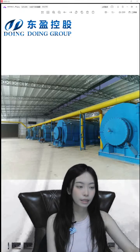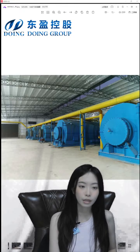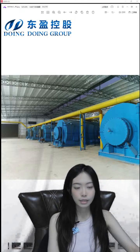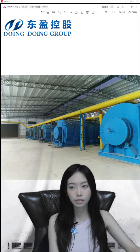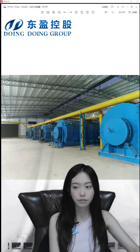The side slag has a very high efficiency, and it's more environmentally friendly, because when we just use the front slag, the feeding door is a slagging door. And when we open the door to slag the carbon black, it may have dust. The dust pollution is very serious. But we use the side slag. It's just underground. We can't see the carbon black. It's all underground in the sealed environment, underground store.